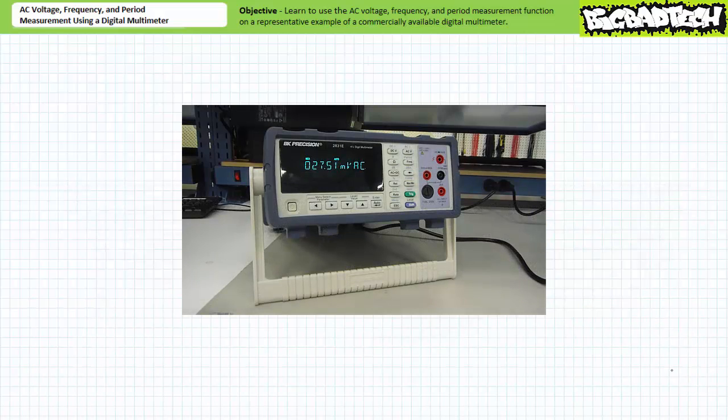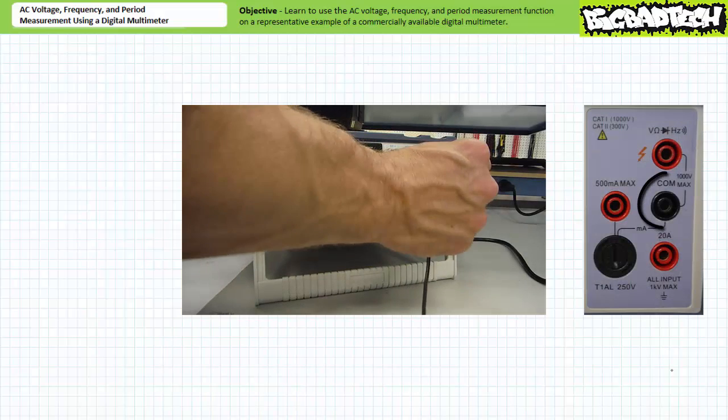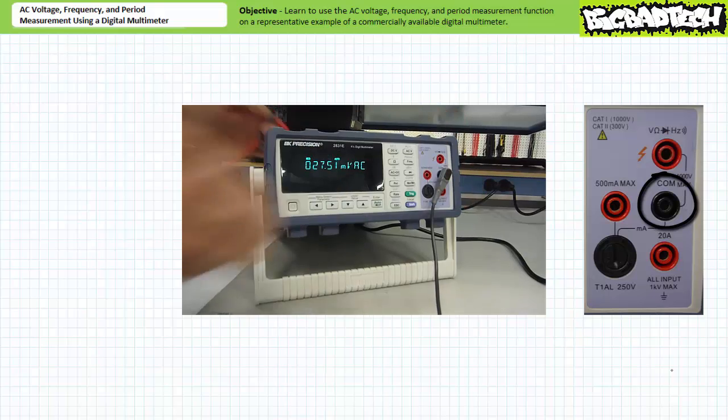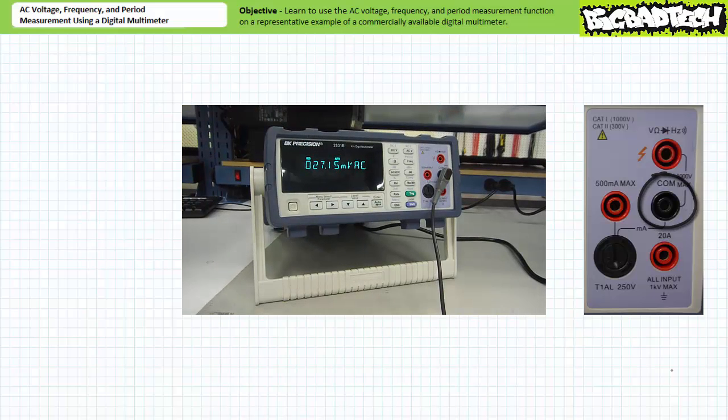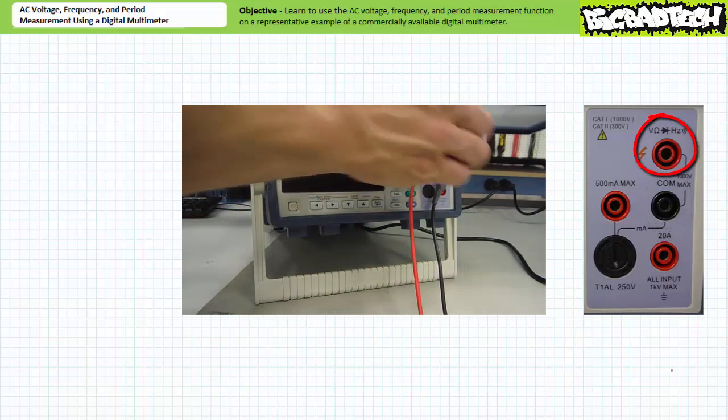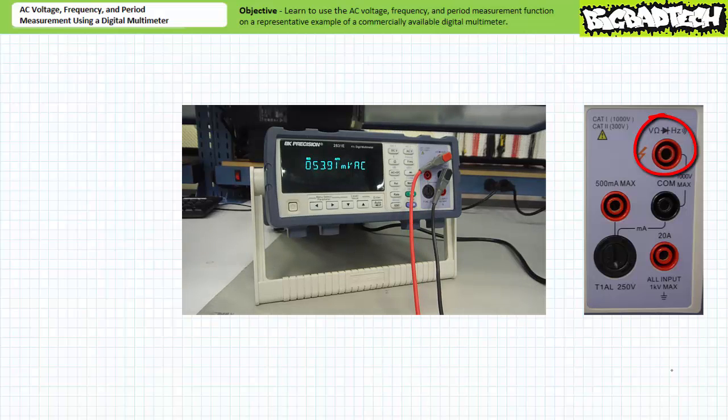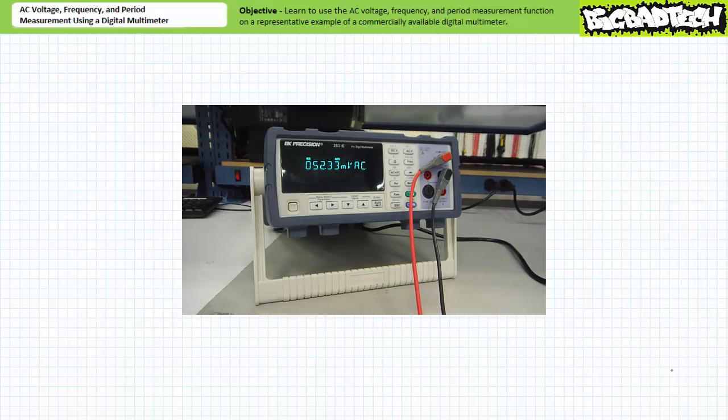Now that the AC voltmeter function is selected, we need to insert the leads. Black lead into the black common hole. This is the lead that will be used as our reference. Red lead into the red hole, indicated with a V, the shorthand for units of volts, over it. Yes, you can put a black lead in a red hole, and you could put a hat on your foot, but that is not its intended purpose.